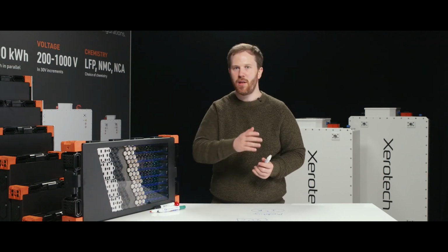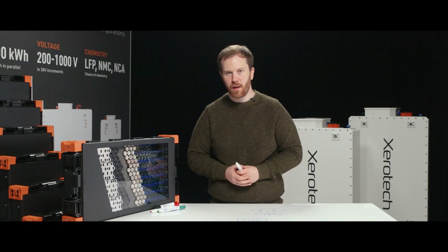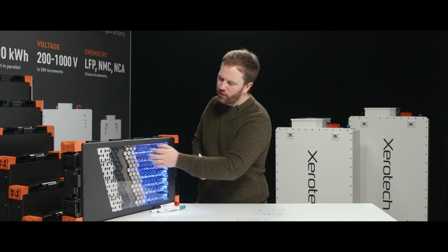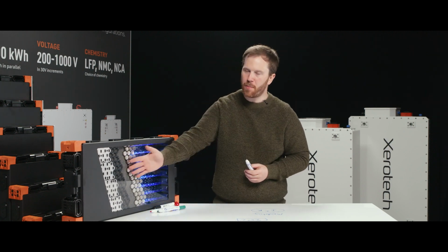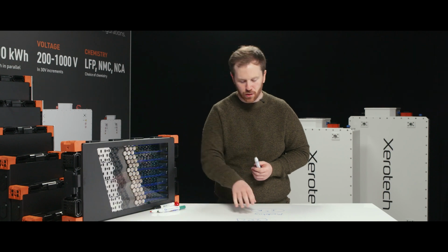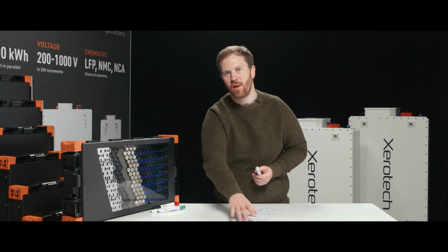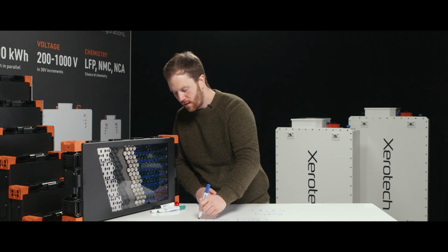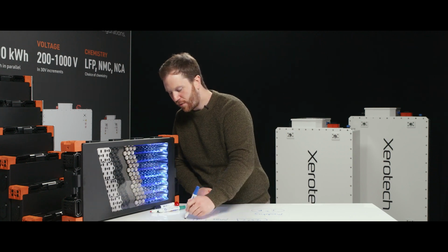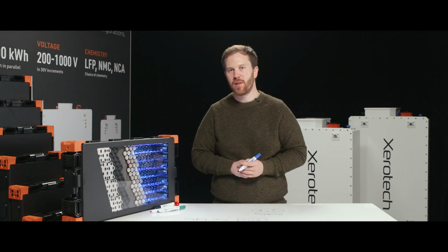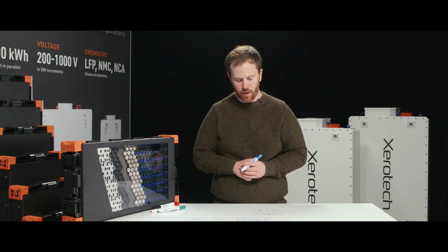So if you're doing a 2C fast charge, you're going to need cooling. And the effectiveness of your cooling, the design of your heat exchanger inside of the pack will influence the temperature gradients within that pack, and overall will impact lifetime. So thermal management, you should always aim to try and do it to maximize lifetime. And if your battery lasts twice as long as the other battery, it'll be half the cost from a system perspective, depending on how you design it.